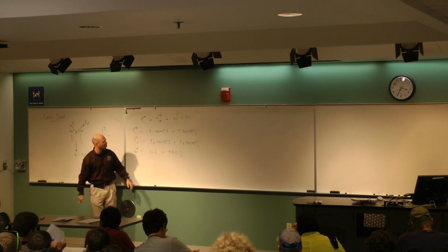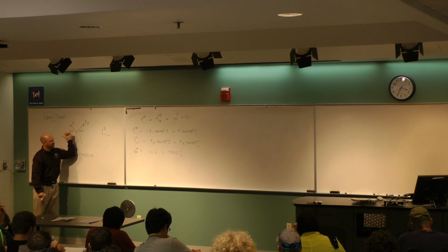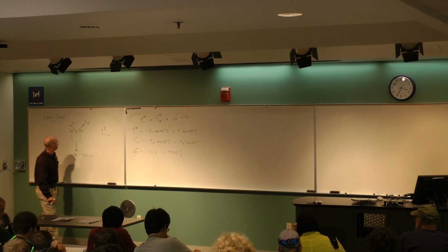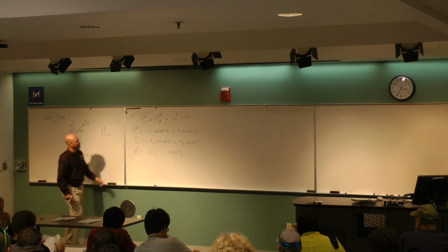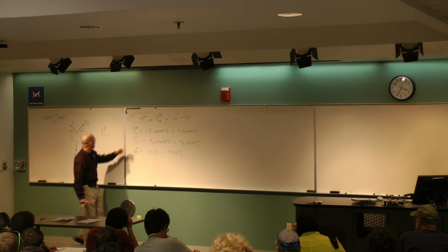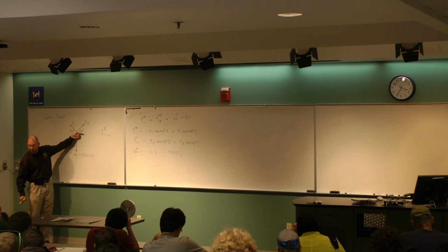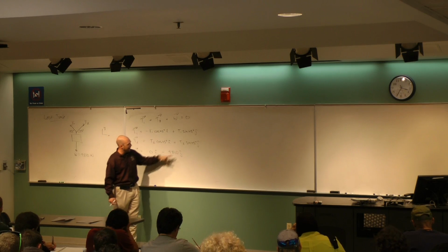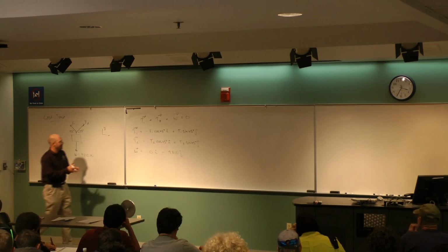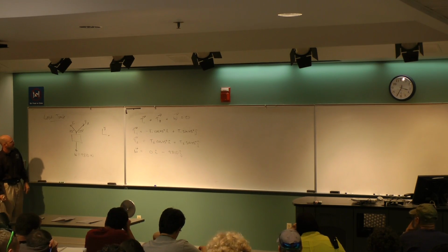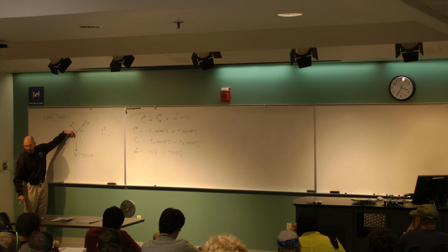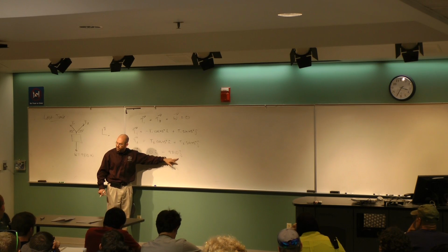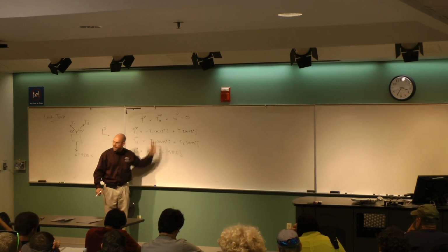And so if that's true, the x component goes to the left, so it's minus T1 cosine 45 i. The y component goes up, so it's plus T1 sine 45 j. If I look at T2, it goes to the right and up, so it's a positive T2 cosine 45 i and a positive T2 sine 45 j. And then finally the W did not have any i component. It goes straight down, so it's 0. And because it's down, it's minus 9810 j. So this is just recap from last time.